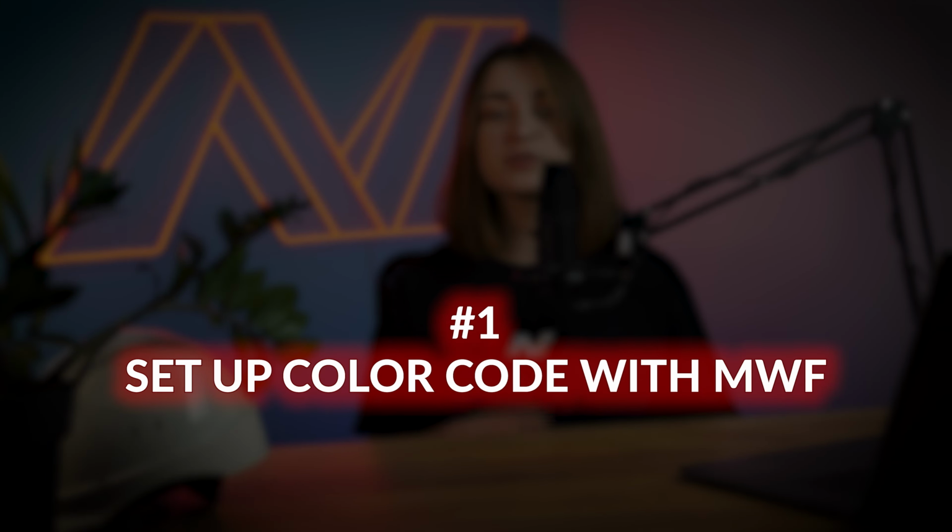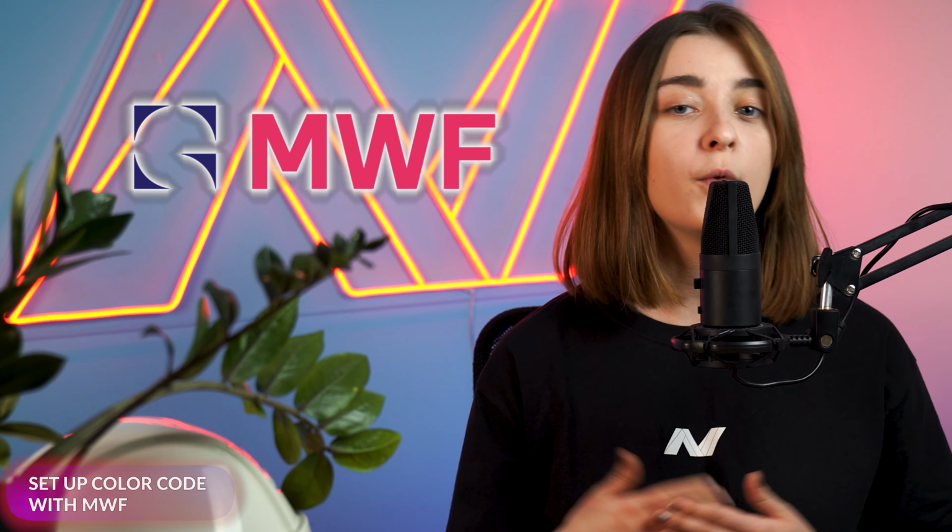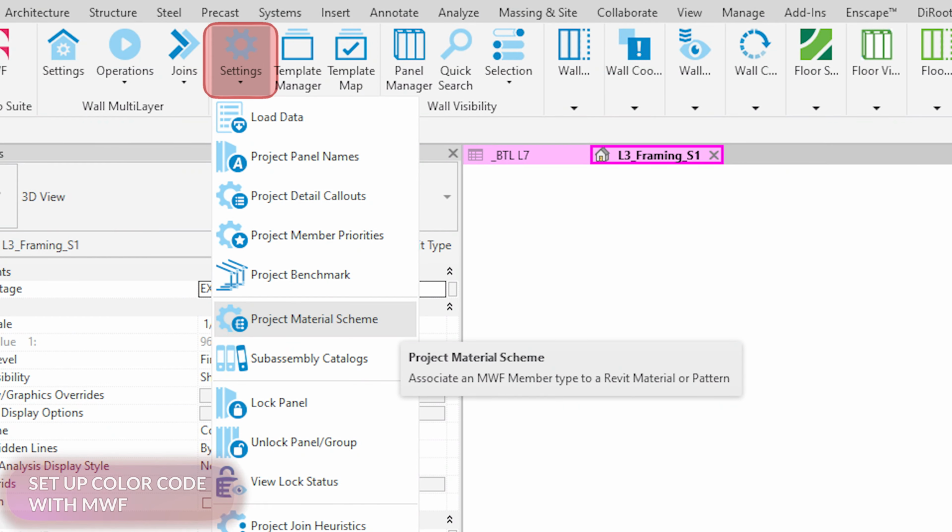The first option for setting up color coding for framing in Revit is by using MWF, or metal wood framing. One of the great features of MWF is the ability to apply color coding to your framing elements by stud thickness or type without making any changes to Revit families. To do this, you need to click on the Setting tab in the MWF tab and go to Project Material Scheme. After this, two types of schemes will be suggested for you.